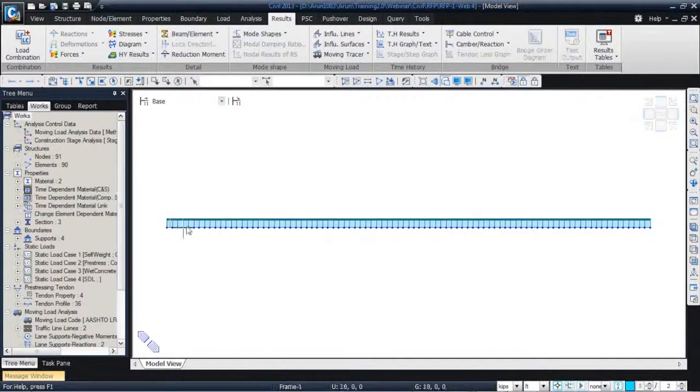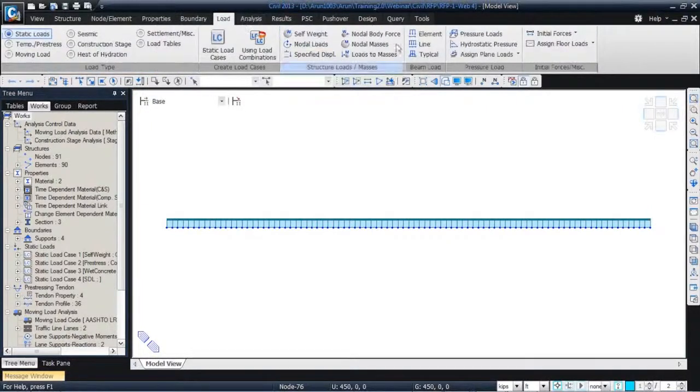I know that my first span is showing the major deflection, and that is my concern. So I'll just increase the tendon area size in the first span, and then use a lower amount of steel in the remaining spans. I can either modify this particular model file, or I can open the one which has a lesser tendon value and then quickly modify it. Let me just stick to this one.